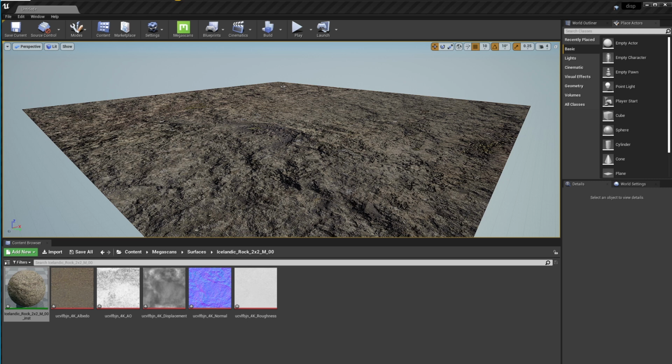In this video, I'm going to do a deep dive into the tessellation controllers, the displacement controllers of the new material, and how they react when using them on a terrain. Now, I'm going to explain that with the static mesh, and then I'm going to switch to the landscape terrain tools that we have here in Unreal.